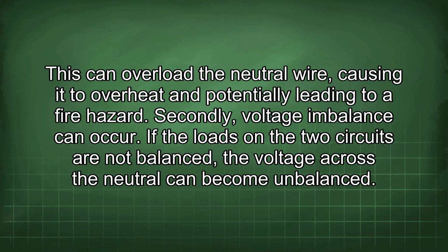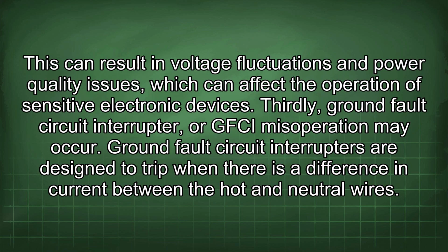Secondly, voltage imbalance can occur. If the loads in the two circuits are not balanced, the voltage across the neutral can become unbalanced. This can result in voltage fluctuations and power quality issues, which can affect the operation of sensitive electronic devices.